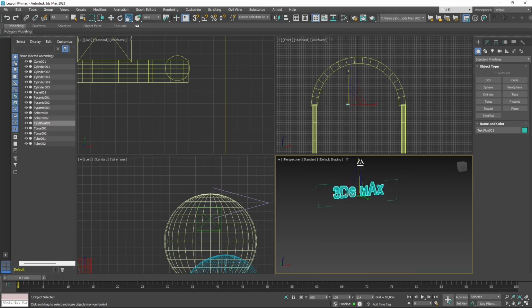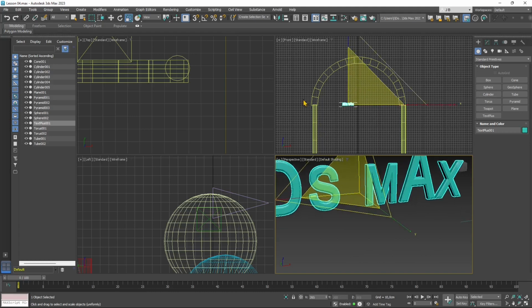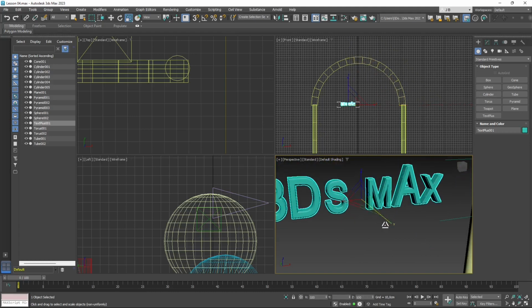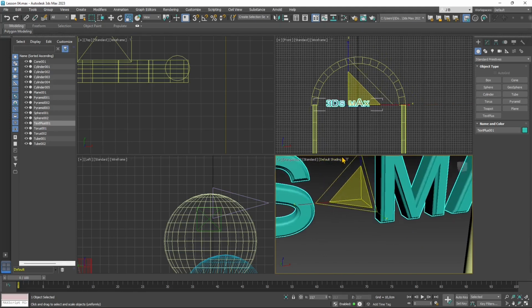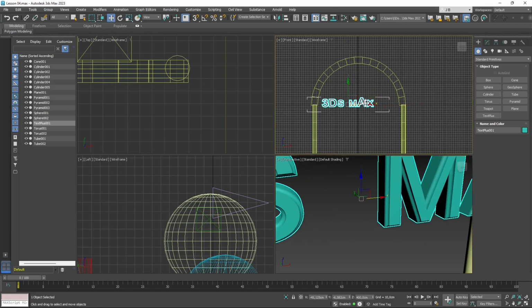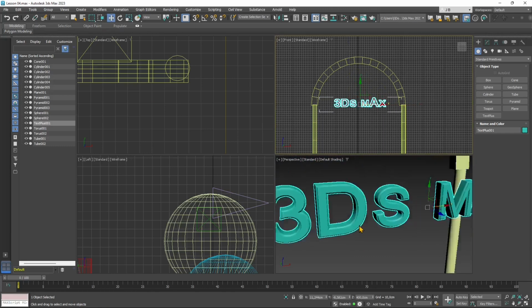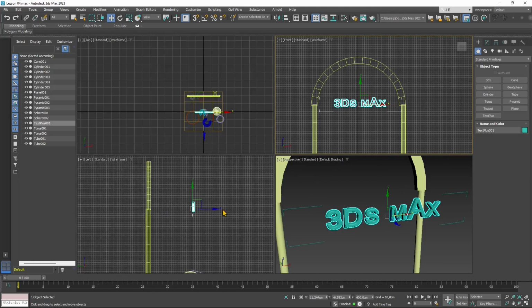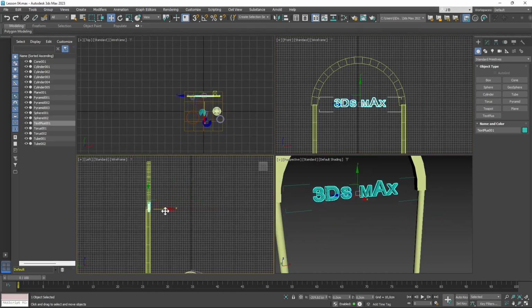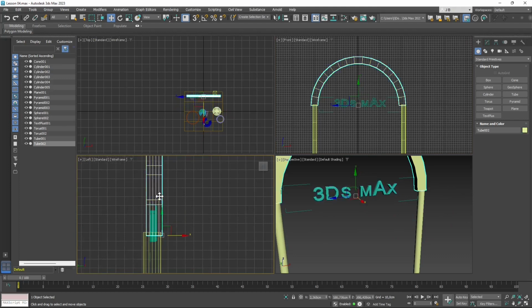And now let's scale, the other transformation. So I can scale 1D, I can scale 2D, and I can scale 3D, depending again on where I pick. So if I pick just one axis, it's going to scale just one dimension. If I select two axes with the triangle in the middle, it's going to do it in 2 dimensions. To scale it proportionally, you need to scale it from every axis. And I'm going to place it right there.